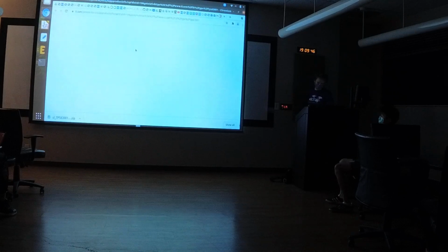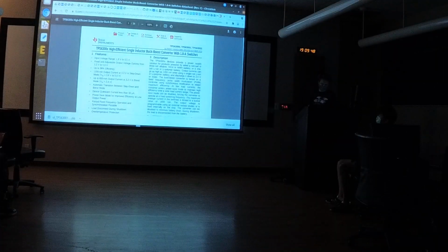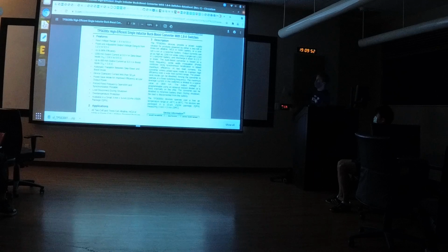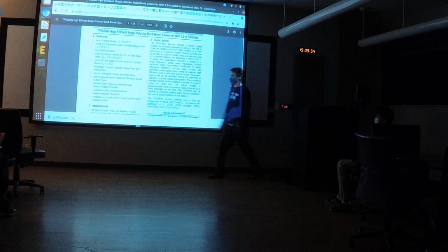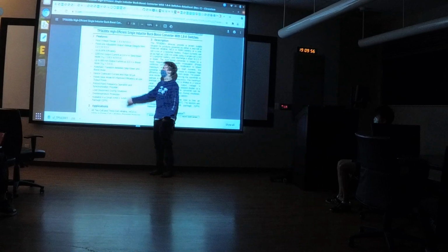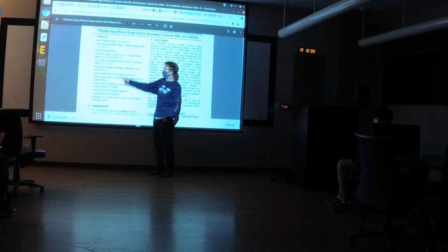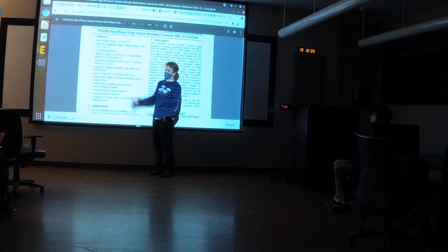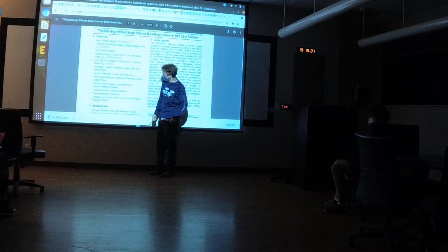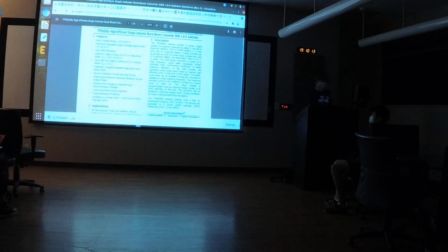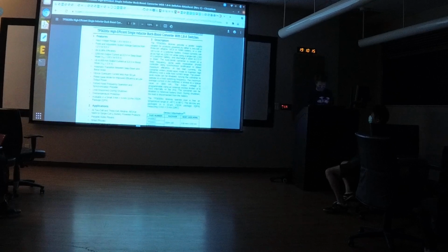Now when we open up the datasheet, it's going to take you to a PDF document which surprisingly describes the entirety of the chip's operations. So remember how I said we want a chip that can take in 2.3 to 5.5 volts? This one can take in 1.8 to 5.5, that's good. 96% efficient, that's good. 1.2 amp output current, good. Looks pretty good, right? Except it's out of stock. Which is why I'm using it, because you guys can't copy me.